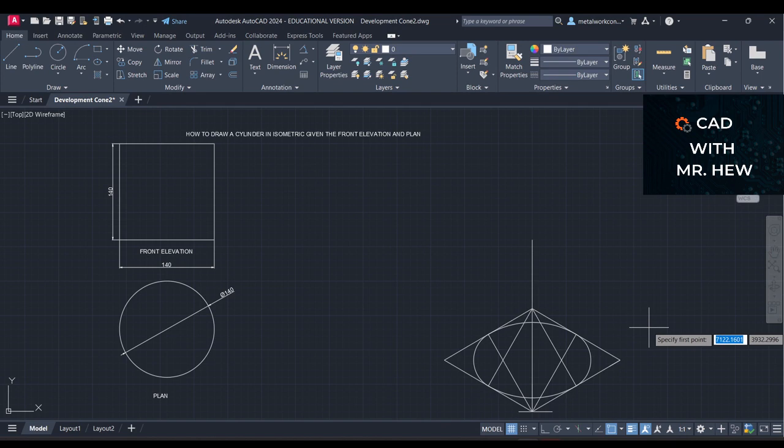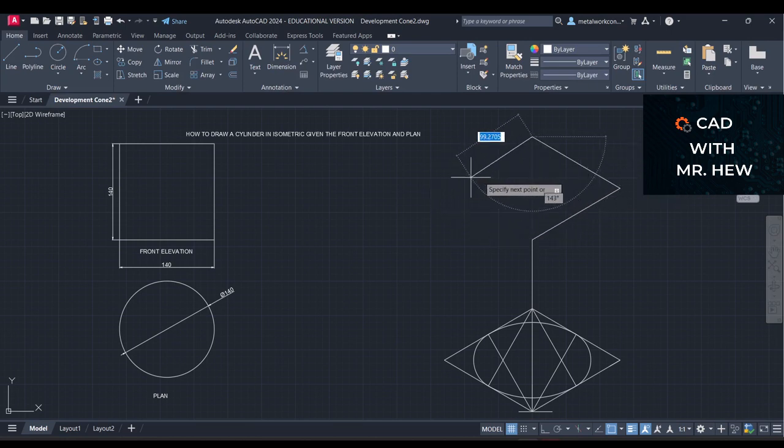All right, so just as how we drew the isometric circle for the base of the cylinder using the isometric square, you have to draw an isometric square from this point, which is the height of our cylinder for today, right? So we're gonna draw an isometric square up there. So we're gonna set out our isometric square at the top. We're gonna come across, we're almost finished with the square, yes.